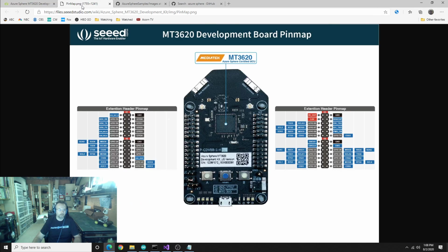and forth. So on Seeed Studio's website, you could get a pinout map that talks about, for each pin, the different protocols that are supported. There's like GPIO, there's analog, ADC, pulse width modulation, all this kind of stuff. But we're going to focus on I2C, which is the SDA and SCL lines.